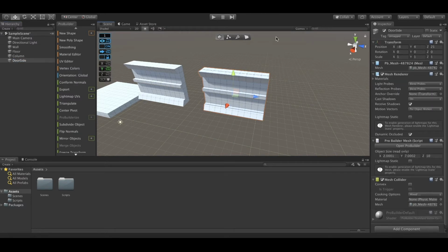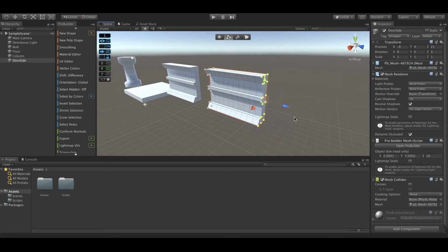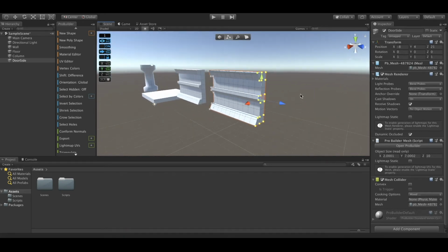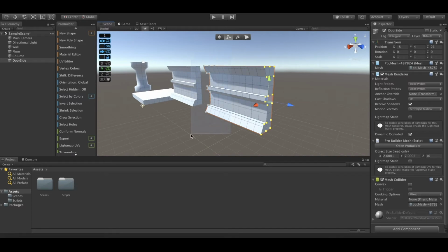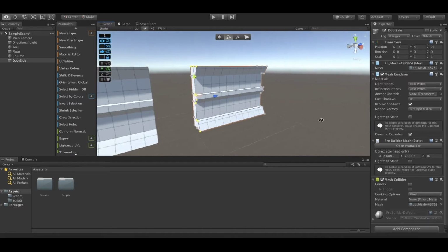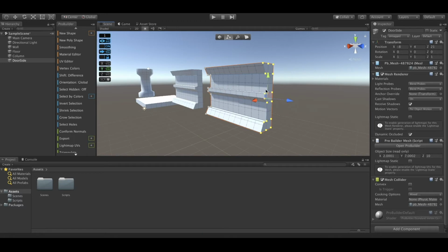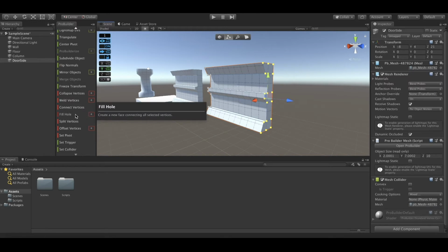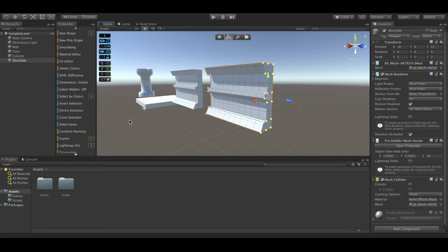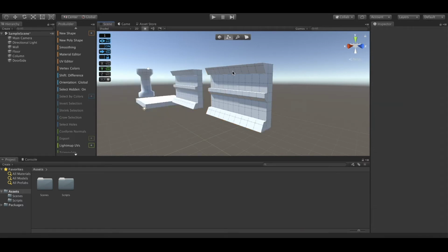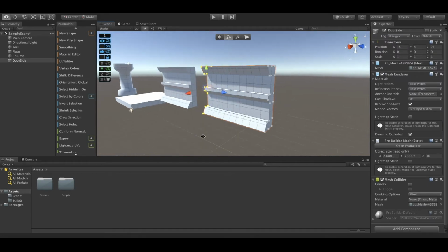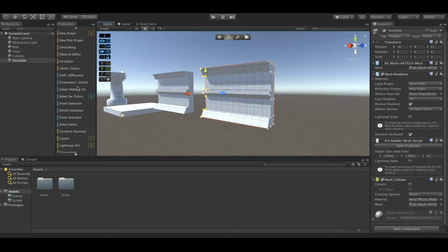All right. And on my door side, I'm going to grab my little points here. And to grab points, if you want to grab a bunch of them, you have to make sure they're all visible. If I try to grab from the reverse side, it only grabs what it can see. So you'll notice if I do that, it won't grab those backside ones, right? So you have to come in and see those to actually grab them. Now there is a setting in here that will let you select stuff in the background, but I think it's actually select hidden off. If you turn that to on right here, then if I go to my object and I select the entire thing, it'll select what it can't see behind it.